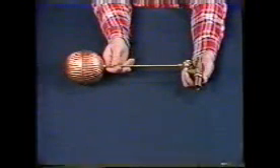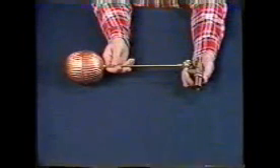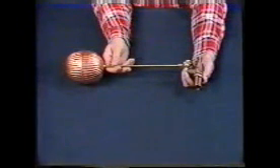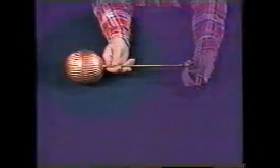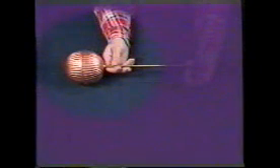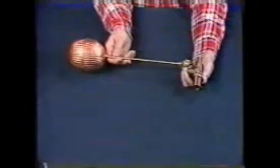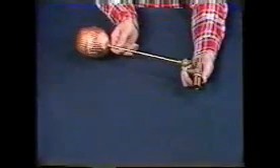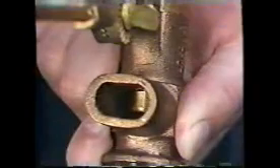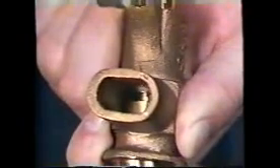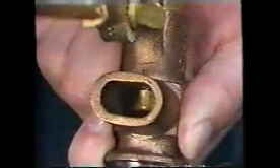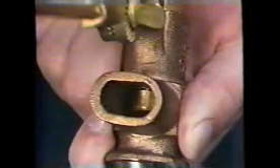The design of this float mechanism is similar to those used in refrigeration systems. It's actually an automatic valve that's controlled by this spherical part, the float. The float is connected to a lever or mechanical linkage. As the level of liquid refrigerant changes, the float rises or falls to open or close the valve. This little demonstration was just to give you an idea of how a basic float mechanism works.